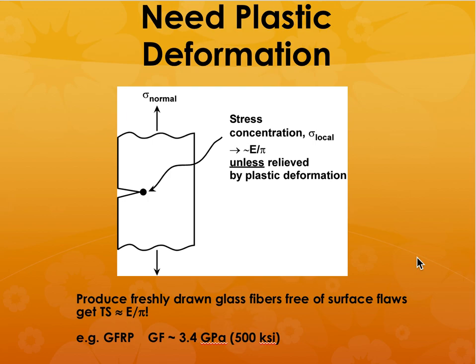And if you had a material that could undergo plastic deformation, then that stress concentration is relieved. So if you do not want a brittle failure, that material needs to have plastic deformation. You understand? Okay?